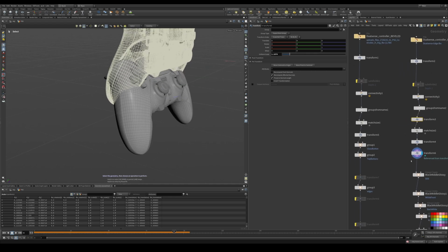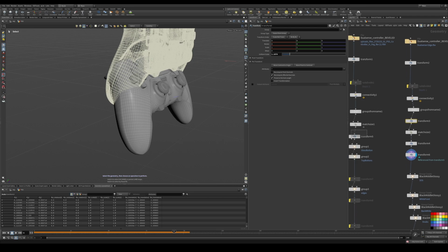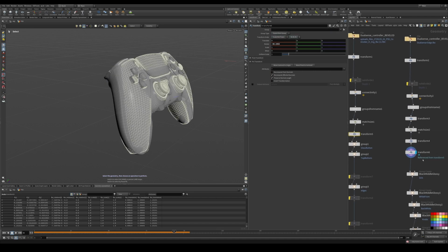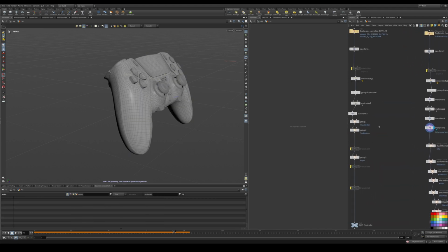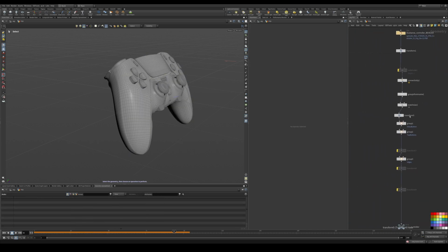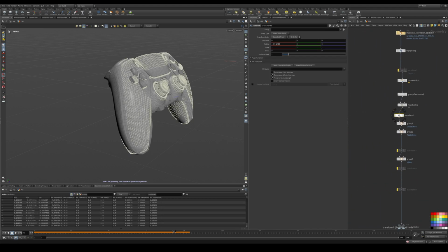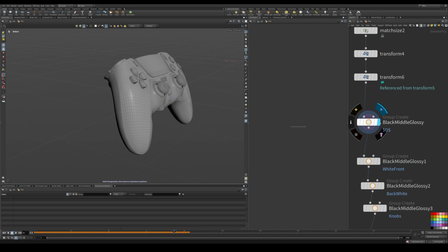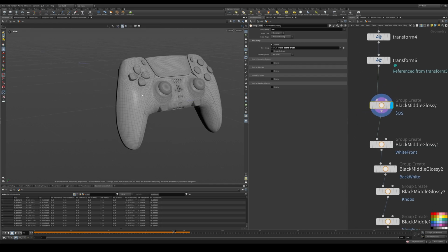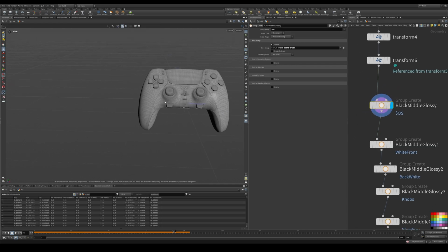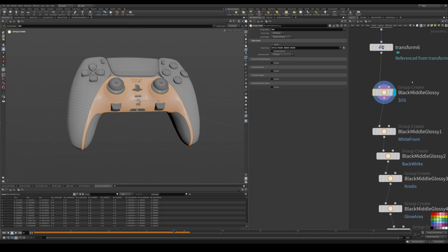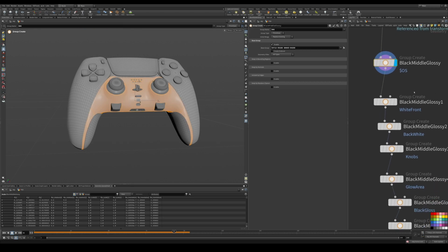This is a link from Transform 5. So the way you do the link, to create the link copy is Control Shift Alt, select it, drag it, you get your reference copy. All right. And then same thing here. I started creating the different groups. This one's not selected. Let me see. There it is. Okay. So middle glass.